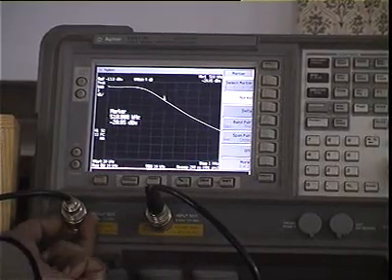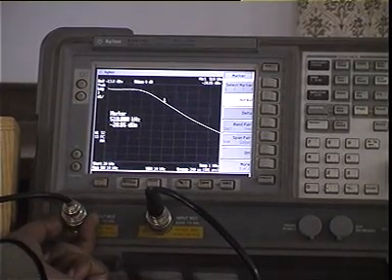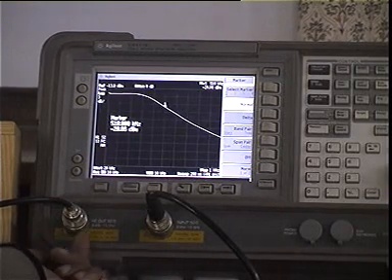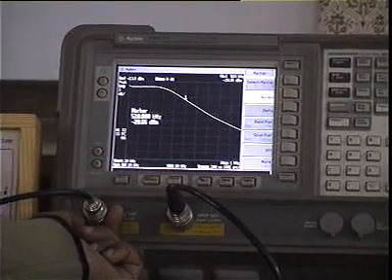There is another similar output available from the spectrum analyzer. Now this output carries a broad set of frequencies from 9 kHz to 1.5 GHz. This spectrum analyzer has a broadband source inside which can generate frequencies from 9 kHz to 1.5 GHz. So now instead of using a function generator and then inputting individual frequencies to the filter, I would present all these frequencies at the same time to the input of the filter. The filter would respond to these frequencies. The output is the filter response which is collected by this cable and then fed into the spectrum analyzer.